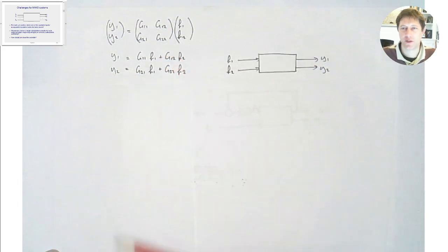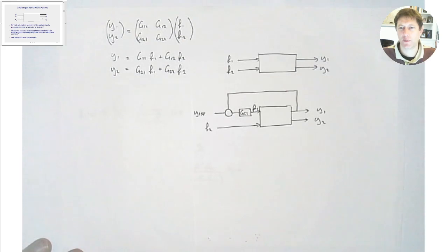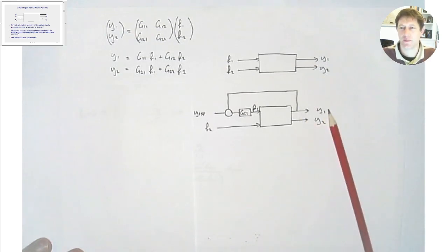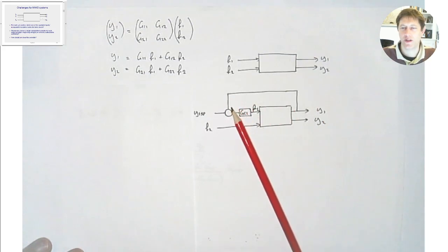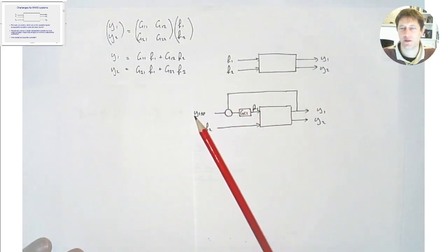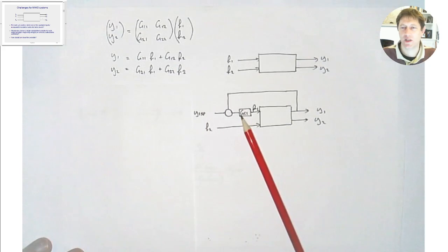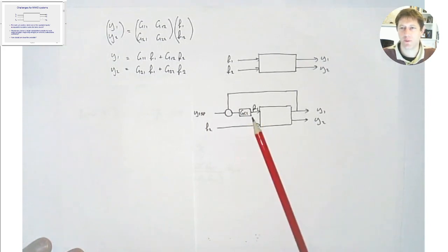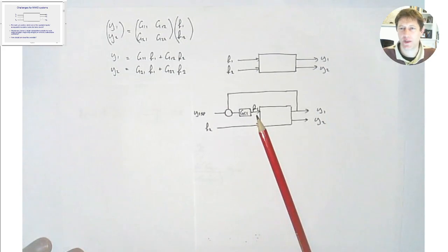So we know that there are practical ways of getting that matrix, but we want to think about what happens now if we decide to make a control loop feedback on this. So let's say we're going to take our output y1, we feed it back via a comparator to y1 set point, and then we take that signal, put it through a controller GC1 in order to control our input F1, and then F2 as it was before. What's the effect of doing this going to be?